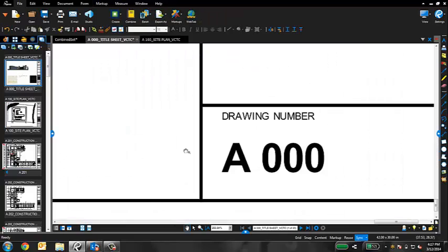With Revu 12 Extreme, you can automatically link entire plan sets quickly and easily using the batch link tool. You can search your files, a folder, a series of folders, or even a set, and Revu will analyze all of your documents and automatically create hyperlinks to the corresponding destinations. In this scenario, we will create a hyperlinked index sheet and link all of the elevation details in the set that we've just created. To search by sheet number, simply click page region.